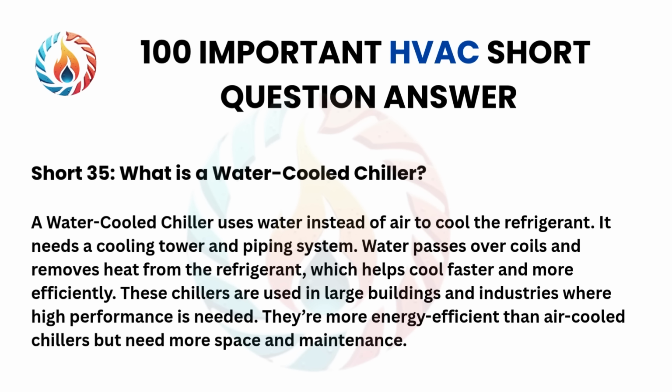Short 35. What is a water-cooled chiller? A water-cooled chiller uses water instead of air to cool the refrigerant. It needs a cooling tower and piping system. Water passes over coils and removes heat from the refrigerant, which helps cool faster and more efficiently.